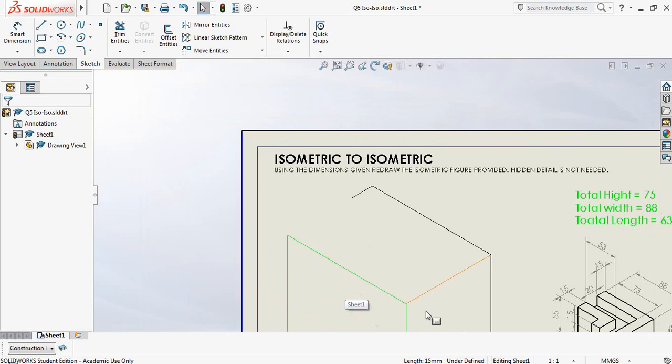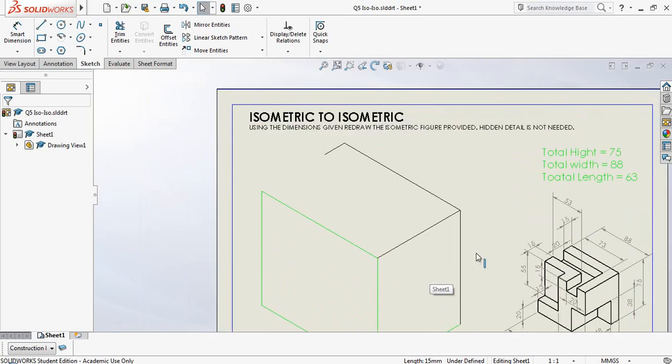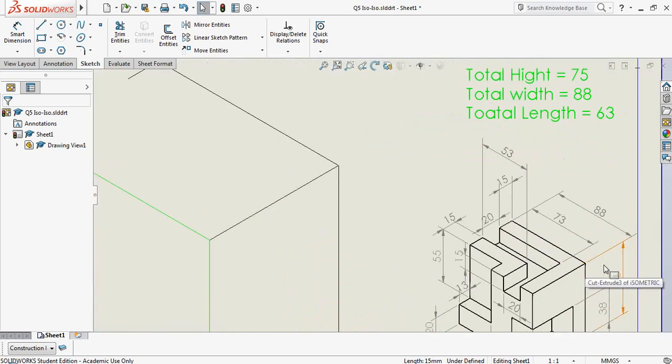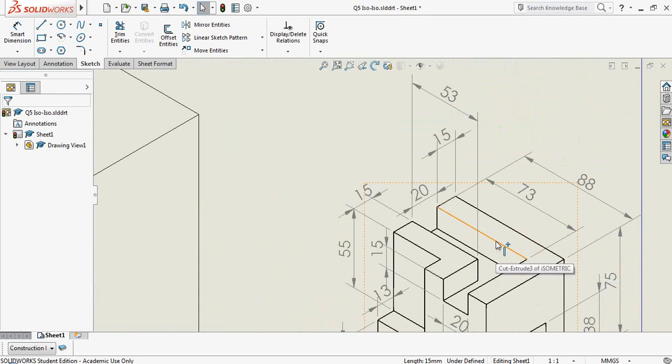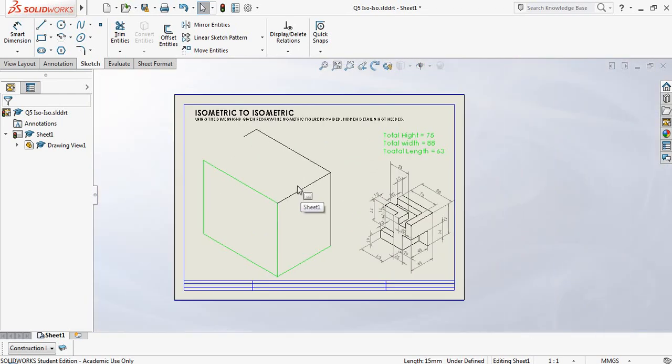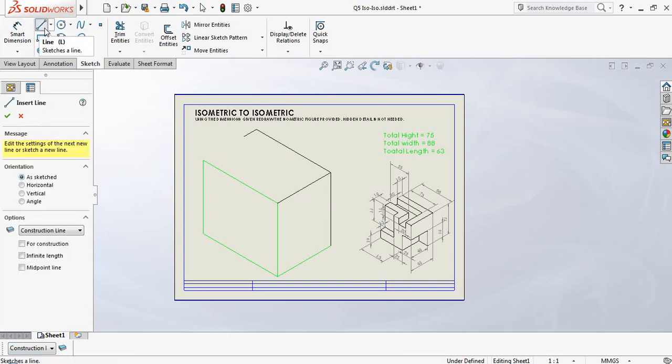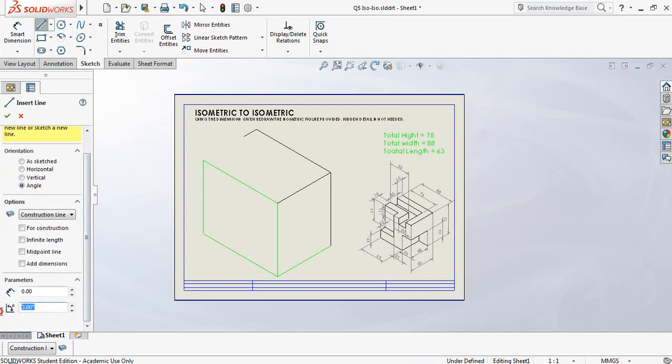Okay, now that I've sorted that out, I'm now going to go at 30 degrees, which is coming back into the side over here, a distance of 73. You can see the distance over there. Let's quickly zoom in on that. That line over there. I'm going to be drawing a line at an angle. This is going to be a 330 degree. Remember, the computer sees it as 360 minus 30, so it's just obviously 30 degrees to the opposite direction.